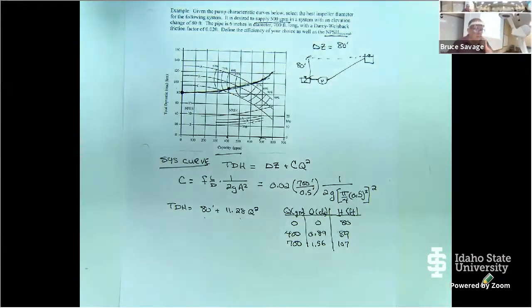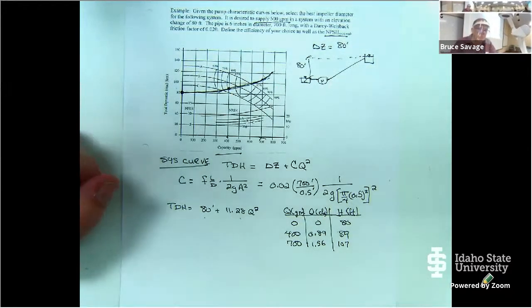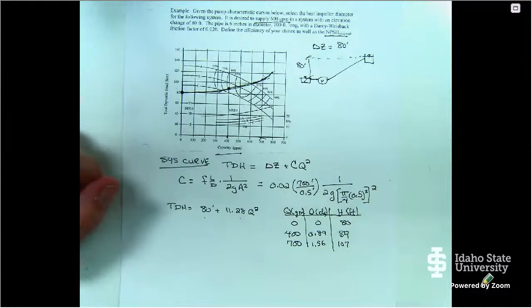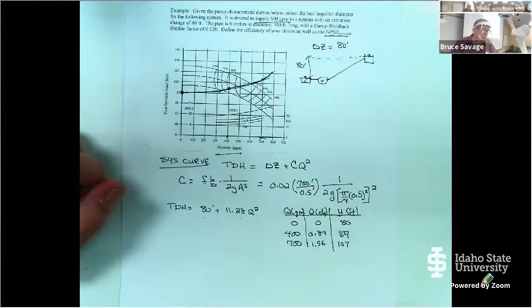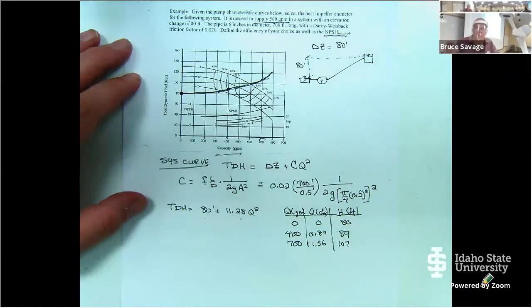Okay. So now I say, all right, I have 3 pump impellers that I want to use. And if my target is 500 gallons per minute, I look at both my efficiency and my target flow rate.